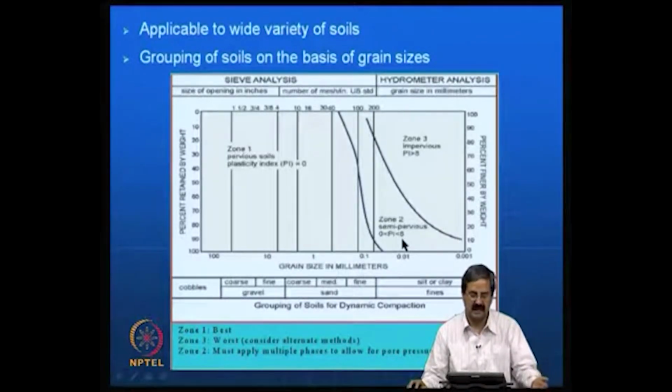In the case of sands it can be a little rapid because you are depending on pore pressure dissipation because of the grain size, but here the grain size being a little smaller you need to look for delayed time intervals, or if there is another way of improving pore pressure dissipation, it is okay.